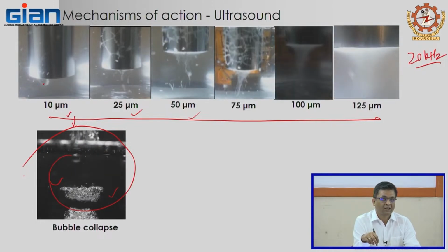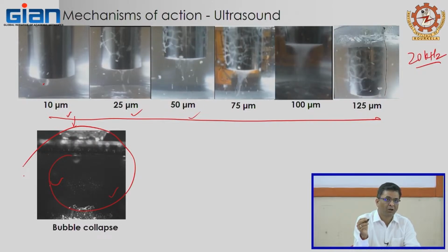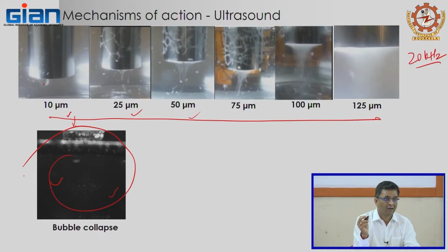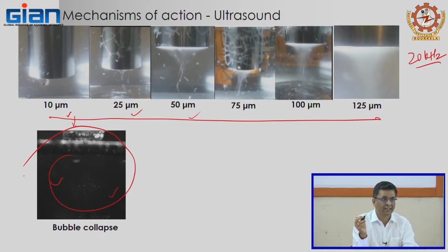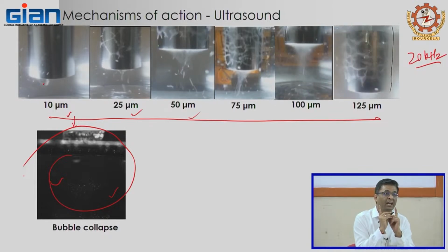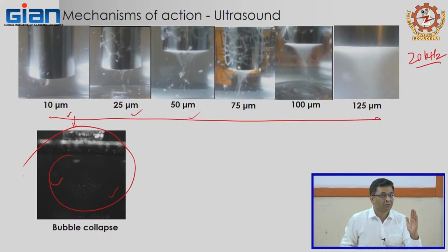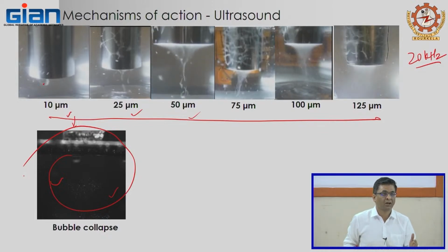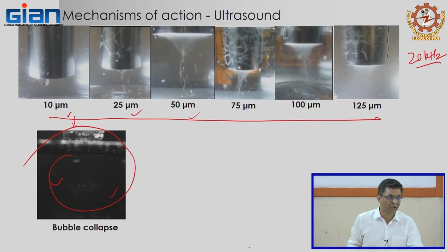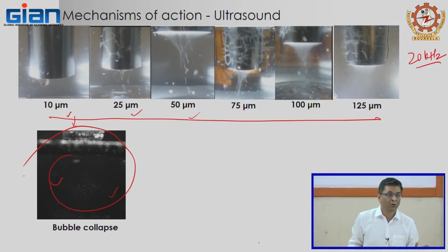When you are using ultrasonic, suppose 750 watt, and if you really want to use 750 watt, take that ultrasonic probe and put it into wood, or any hard surface. Ultrasound will always try to vibrate at the same amplitude. If it doesn't get enough room to vibrate, it will use the full power, and if it's not able to use full power, it will go, that is overloaded. For that reason boosters are used. So if you put it in water, it will make a loud noise.